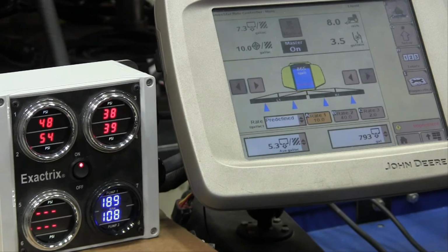Wow, that was quick. That really came up. A couple seconds, a real quick change. Let's go back down. Don't forget, listen for that click in the manifold, and that's when the pressure is really dropping. There it is. So that's a pretty good indication, just that visual, and 2.4 seconds from the sound of the accumulator.